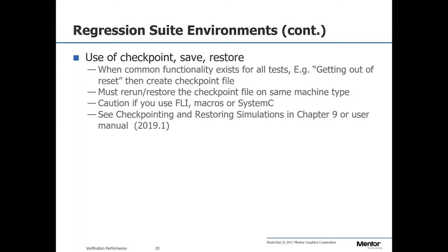Let's say that training phase takes half an hour to negotiate back and forth and set up the PCI link, and then we're ready to go. Then I run some interesting simulation, and that takes 15 minutes. So it was 30 minutes to get to the link train, 15 minutes of interesting simulation. Now I want to run another test, and it's going to be 30 minutes of PCIe link training, and then 15 minutes of interesting simulation, and again, and again, and again.